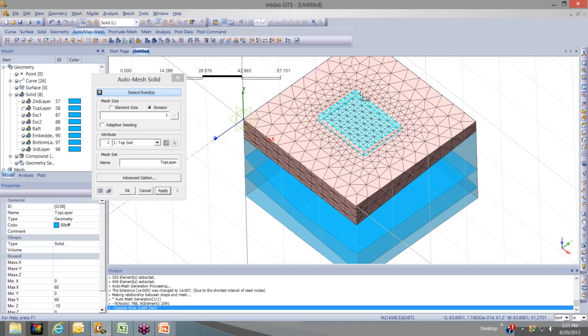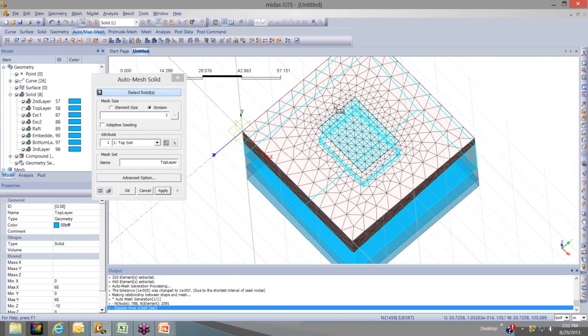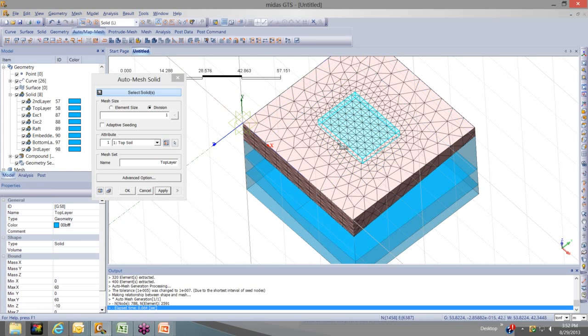Okay, so one thing before I continue, as you can see, it's very important that whenever you have a large opening or an excavation point, the mesh becomes finer around it. As it gets closer to the excavation, the mesh goes from more coarse to more fine. The reason we want the mesh to become finer at these areas is to get a more detailed analysis later on. The area right around the excavation point will be of most interest to you. You want to check the stresses and the deformations there. So in order to get more detailed results, you want a finer mesh set or elements here.